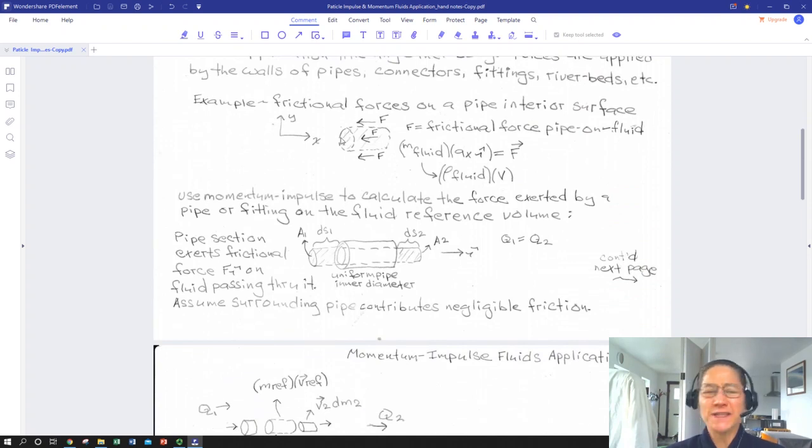So we're going to start with a 1D example. Many of you might know that fluids moving through pipes and other containers are subject to frictional forces like anything else that moves, and that's a big deal when you're designing water systems. And in fact, you need to over-pressurize in some cases parts of it near a reservoir or a well pump station to ensure that something at a far branch that's been subject to a lot of frictional losses will have enough pressure that it can meet fire requirements, etc.